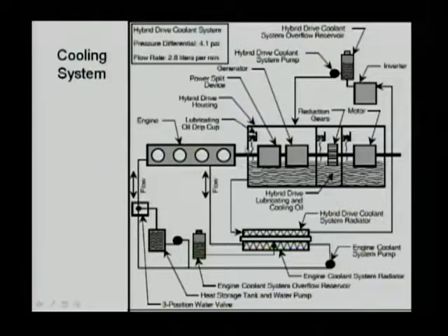So this system is cooled usually at a lower temperature. A typical coolant temperature is about 70 to 80 degrees C in the power electronic motor cooling loop. But it's usually around 100, maybe 110 degrees C, or even 120 degrees C on the engine side. It depends, of course, on the season and the operating condition. That gives you a rough idea of how those electrical motors and power electronics are cooled, and how it is designed in a Prius, a system similar to a Prius hybrid.